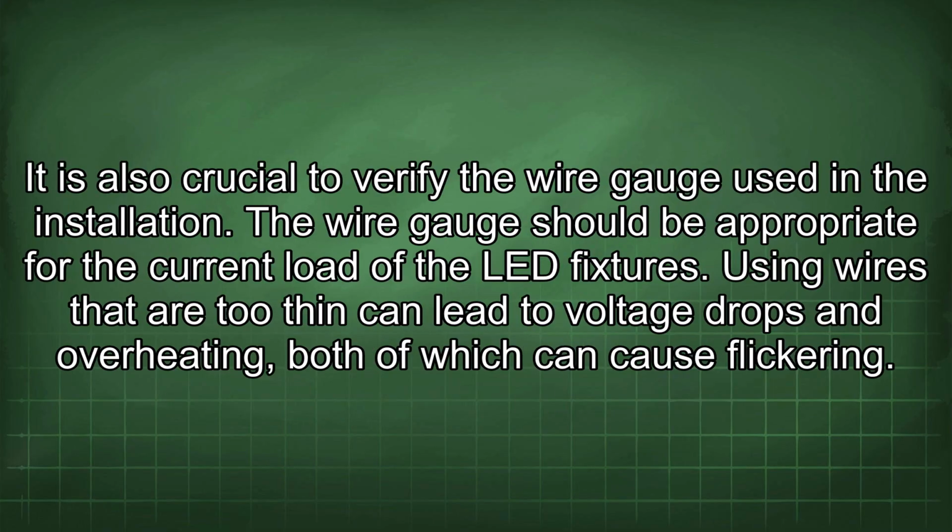It is also crucial to verify the wire gauge used in the installation. The wire gauge should be appropriate for the current load of the LED fixtures. Using wires that are too thin can lead to voltage drops and overheating, both of which can cause flickering.